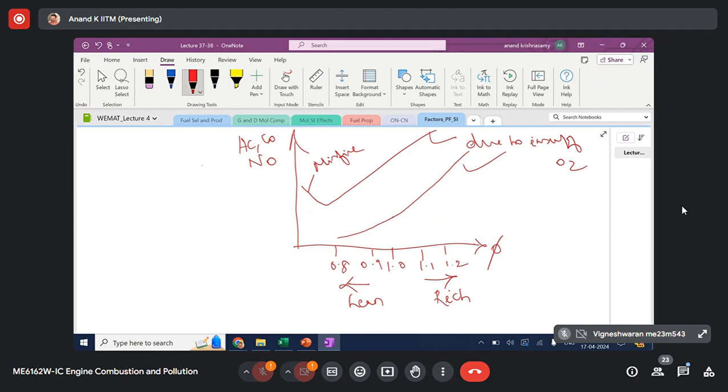When you don't have any combustion at all, you cannot talk about partial oxidation. So it is completely missed combustion. Misfire is the process where combustion is completely missed. So you will have that contributing to HC but not to CO. CO will continuously drop when you move towards the lean region. That is a trend we have already discussed.